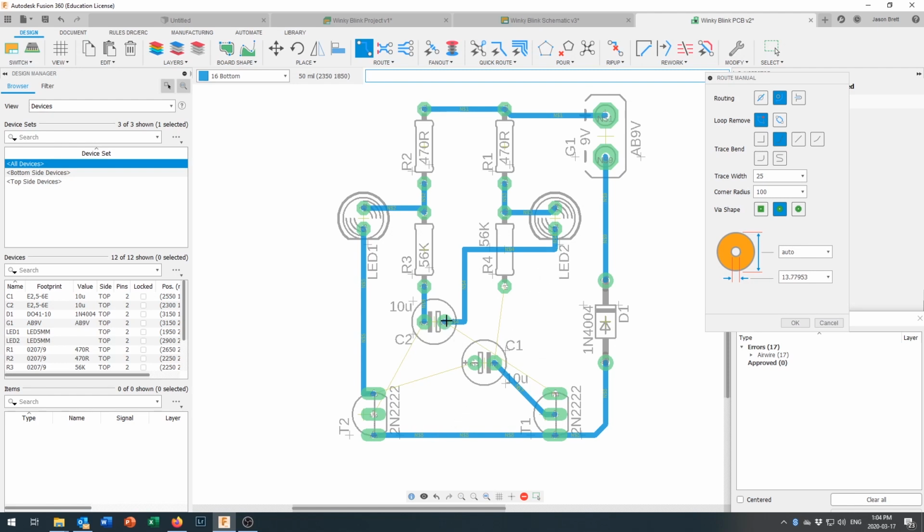Now, this one says this needs to be connected to right here. And again, you're probably looking at that saying, uh-oh, I'm trapped. There's no way out right there. But remember that this pad is already connected to this pad right here. So if we take this line right here, bring it right up there. See how that air wire jumped right up there and it says, oh yeah, you can connect here.